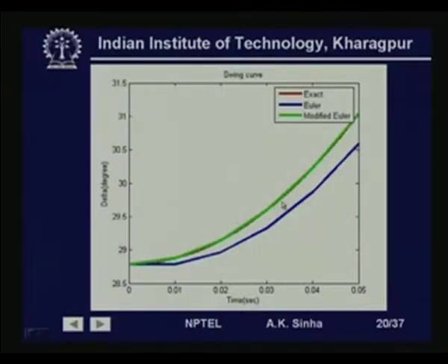So, instead of the accelerating power, which is P m minus P e, where we had taken P e equal to 0 for all this period, that P e now will have to be replaced by this P e relationship, where the values will keep changing with the delta angle. So, using this we can find out again how the swing curve evolves, that is, how the machine power angle or delta angle changes with time once the fault is cleared. Okay, so this is how we can plot the swing curve.